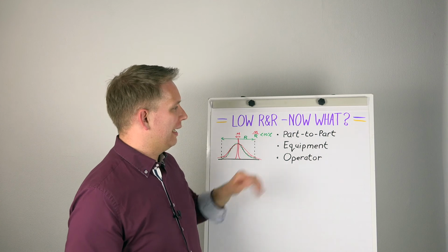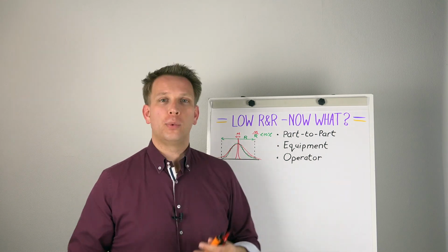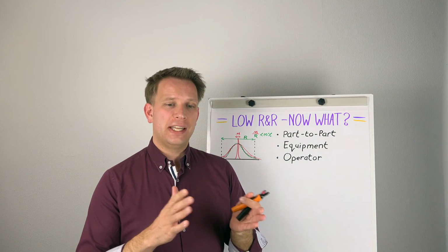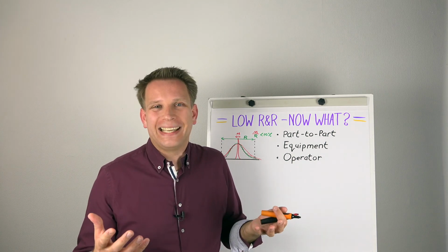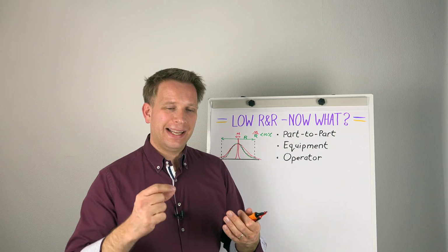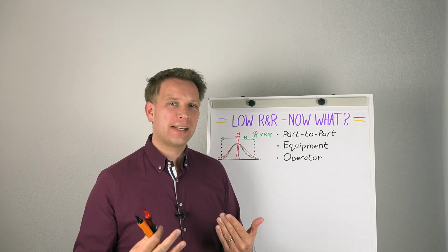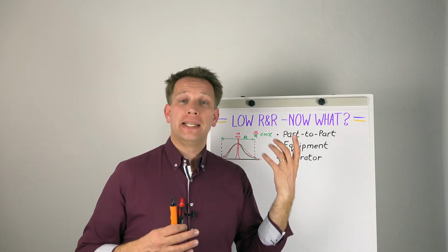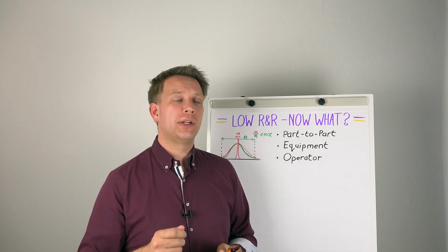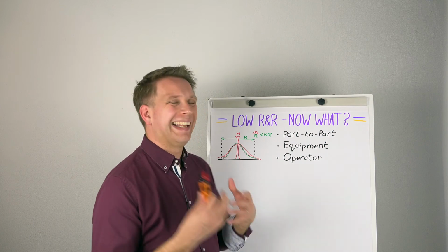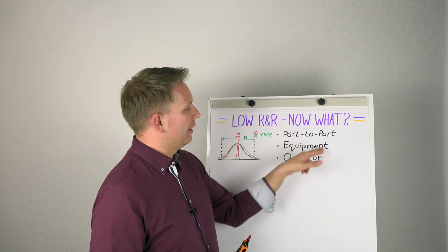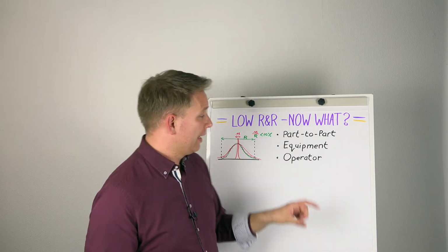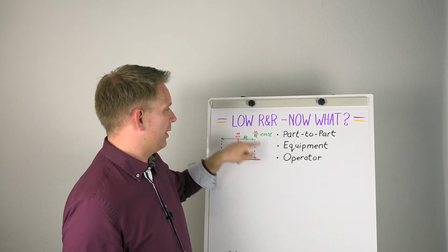When we have equipment variance, then we are really looking at the machine probably having difficulty repeating the same result, so getting exactly the same value because it has slight changes every time, and/or we have indeed a difficulty in reading, even when you try to read it at the same time, in the same way every time, it's difficult to read. And then the part-to-part, as I said, these two we add up, divide by the part-to-part.